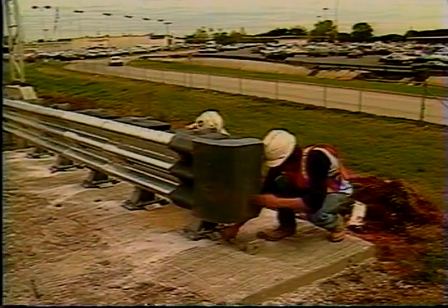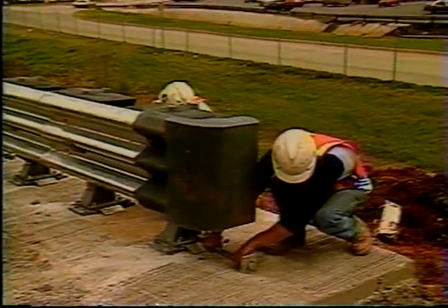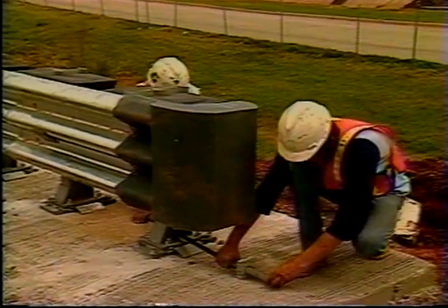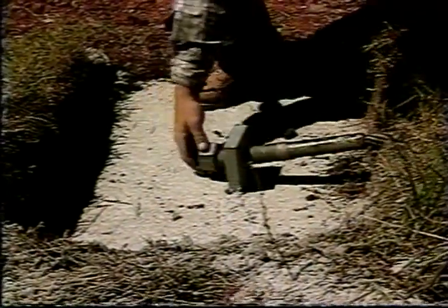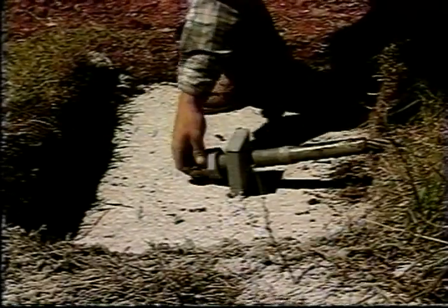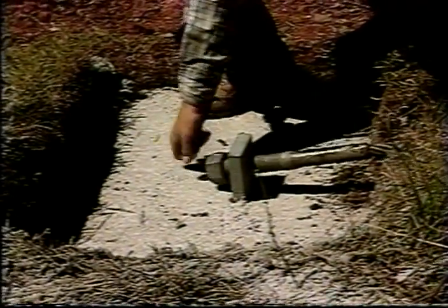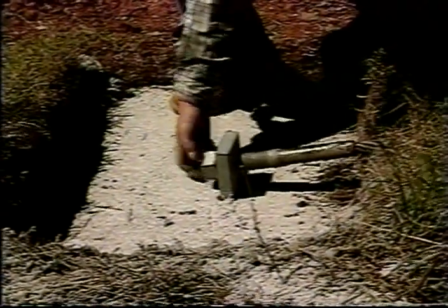Place the front threaded end through the first post and on through the anchor. Install 1 square washer and nut on it. The rear anchor threaded end must go through the rear anchor, using as many square washers as necessary to install the nut without bottoming out on the threaded section.